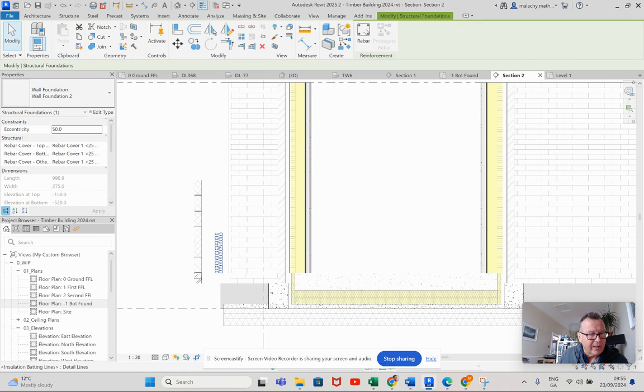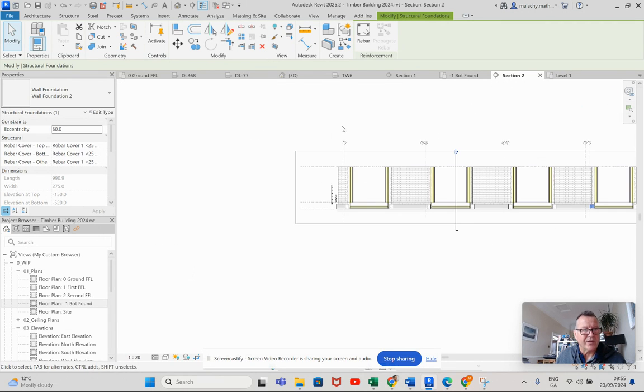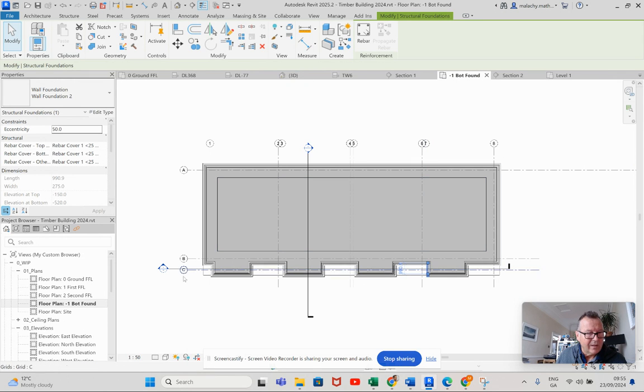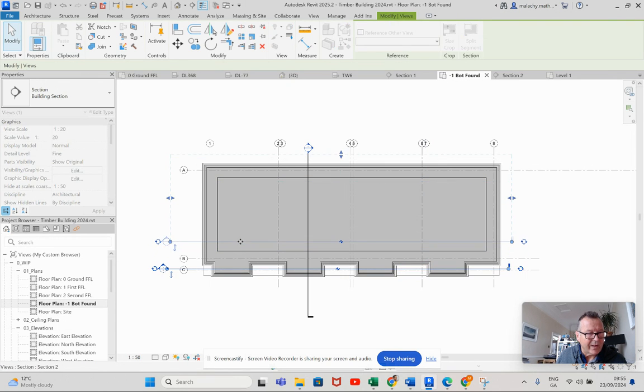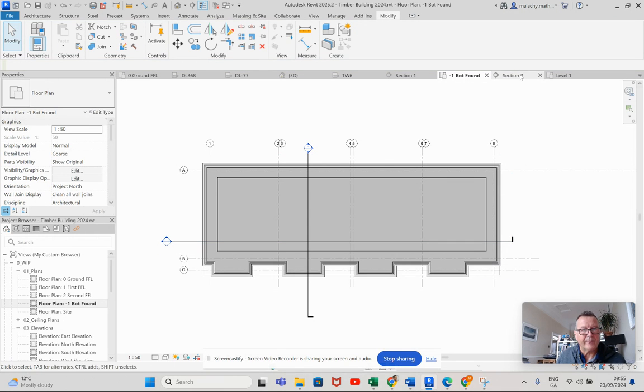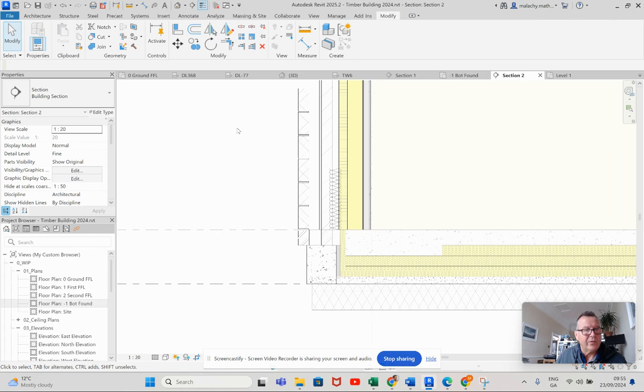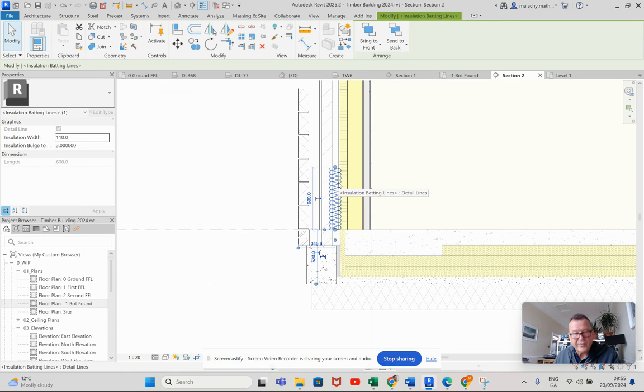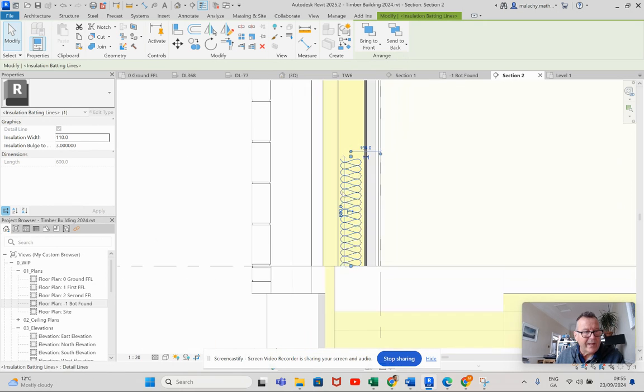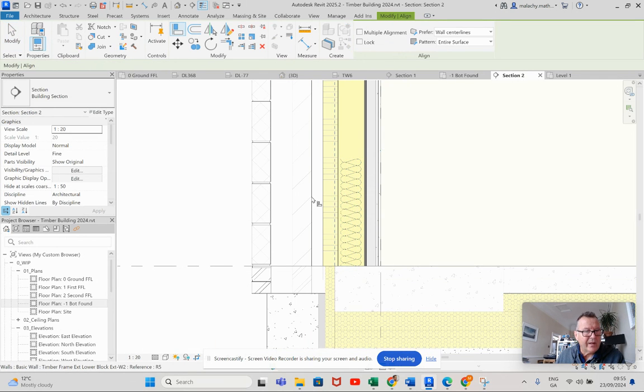Okay, and these are my detail lines that I just popped in for on that section. Now look what happens when I go back to here. I take that section and say, right, I'm finished with you there. I'm going to go back up to your regular position here. Now what I'm going to do is make sure that my grids are aligned. I'm just going to take that one and use my arrow keys to put that detailed insulation graphic in place here, and then I'll align by hitting tab to there, and I'll align that one into position here, and I'll do these two as well.